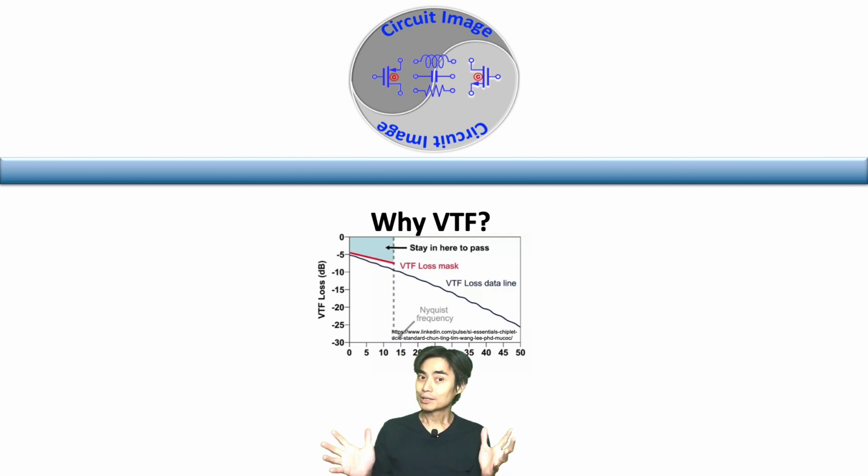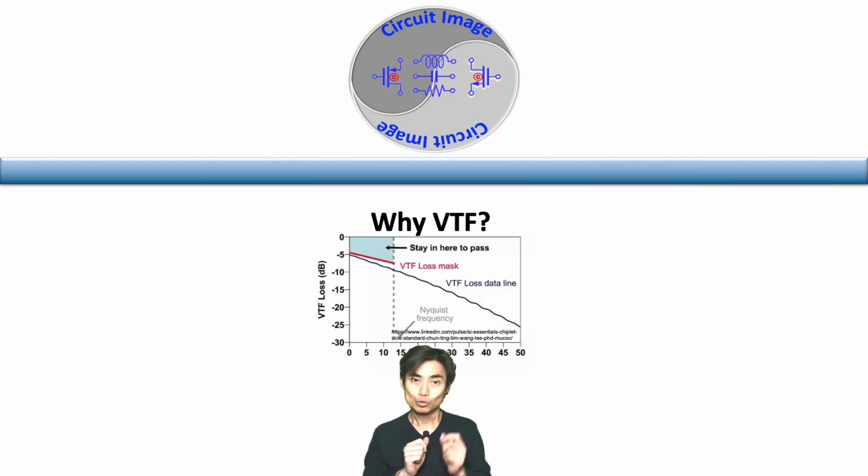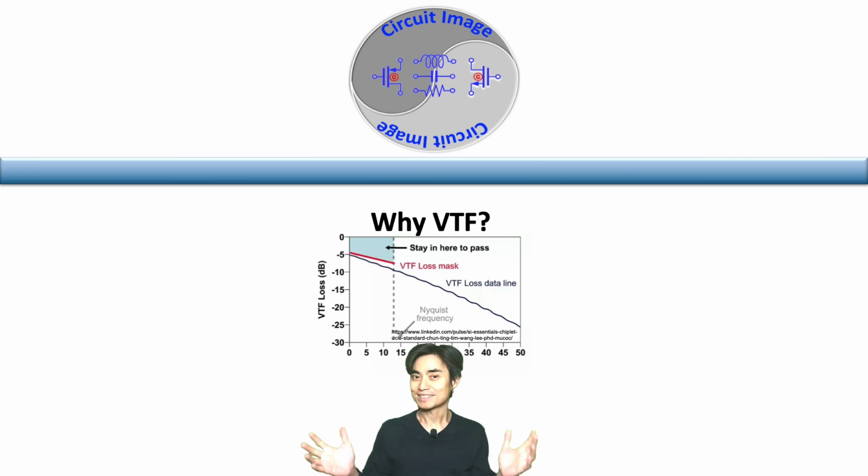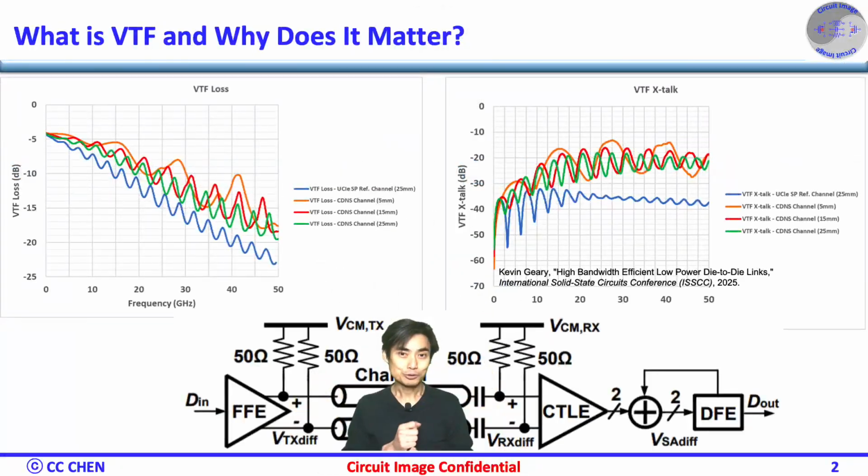Before exploring its impact on SI debugging and verification, it's important to understand what VTF is and how it differs from traditional metrics. The voltage transfer function VTF represents the ratio of received voltage to transmitted voltage across frequency.